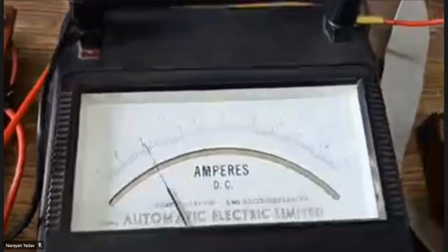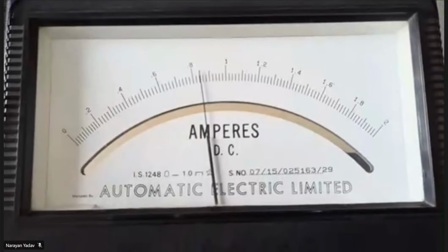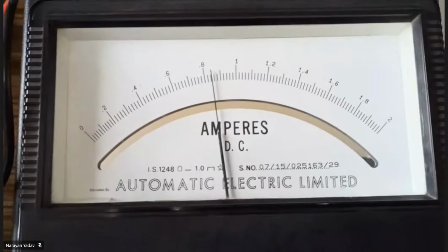Now 4.4 milliamperes. The fundamental component of output voltage is 50.2 volts and the THD is 1.6%. Now we will change the load again and we will set the load at 31 ohms. Now the input side current has changed to 0.84 amperes.